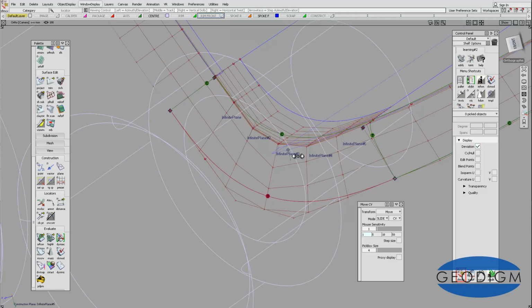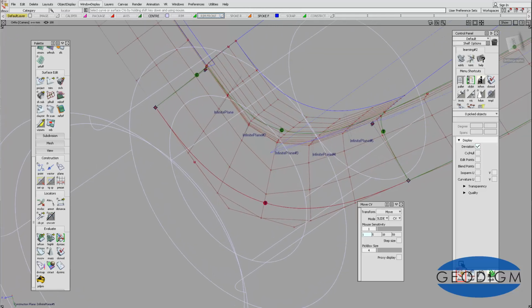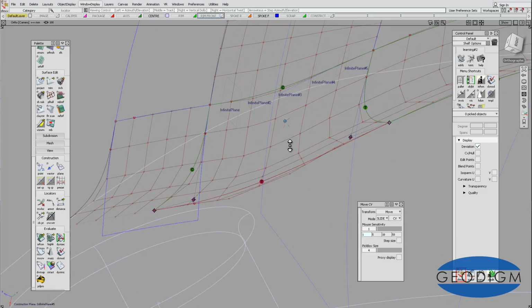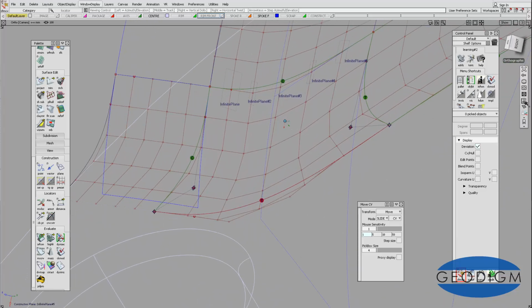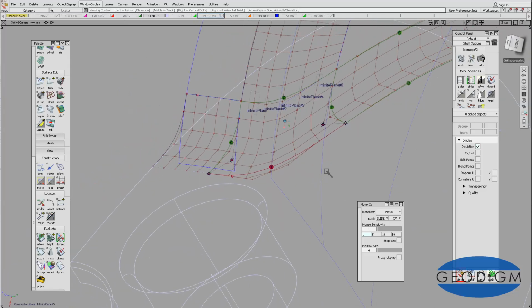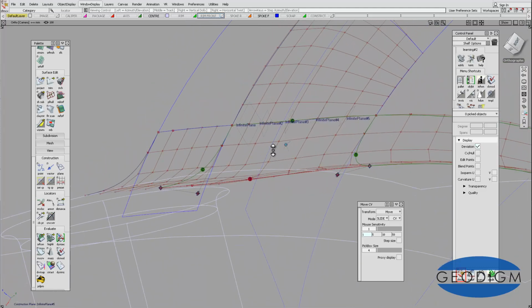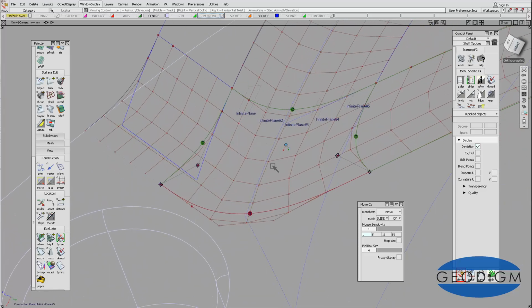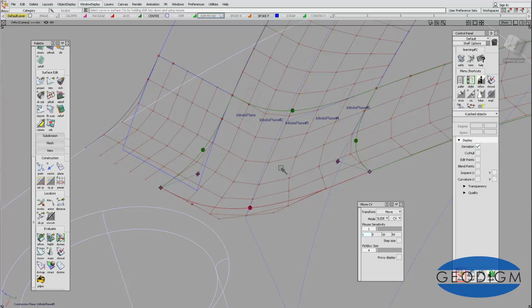And if you look in, again the middle one's the real problem one, because it's just undefined where it wants to be. So this one is a bit too far out this way. So what I'm going to do is again move it along the correct tangent line. So you use that one, then we're less likely to break it, although there isn't curvature matching on the outside edge at the minute, it's less likely to break it if there was. So we're going to then do this one, and this one's very important that we move along that line there so that we don't break the tangency, although the tangent is broken at the minute, but we'll fix that in a minute. But it's a combination of getting the continuity correct and also the I'm just changing the tumble mode there. Also the continuity and the patterns of CVs are both important, and so you've got to work on one and then the other and go backwards and forwards.